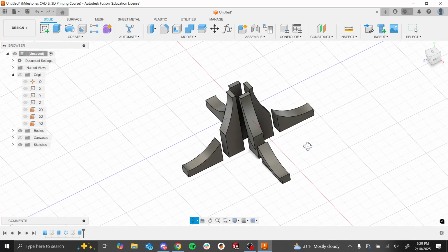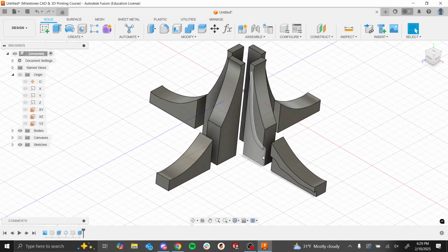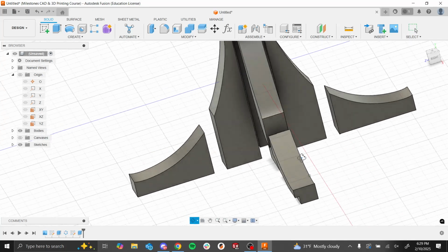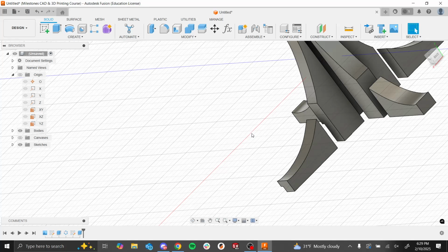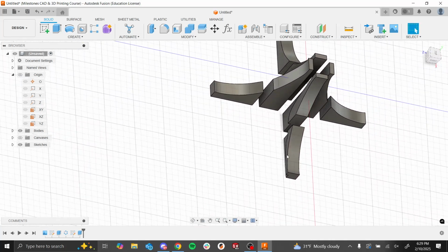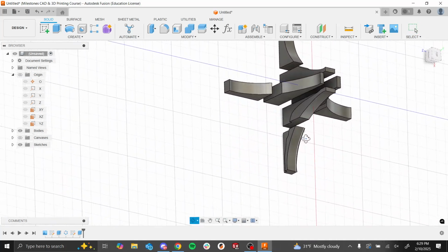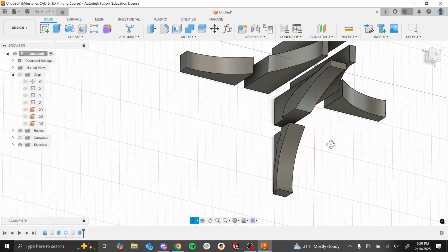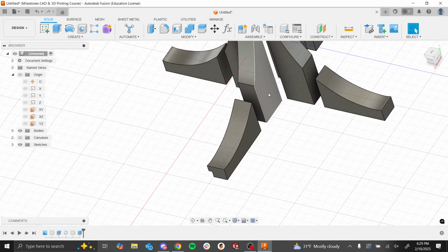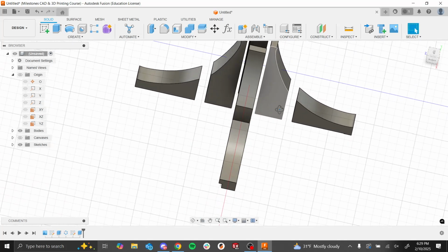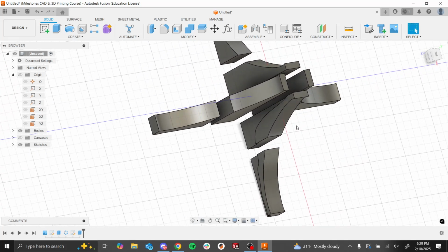Okay. So now that we have this, the other thing we want to do is mirror that same feature onto this side. Again, there's more than one way of doing it. You could just do the extrude just like you did for this side, but instead of using this face as the start, you can select it as here. So you can do the whole object thing, but you can also do it as a mirror, right? Again, there's no wrong or right way to do it.